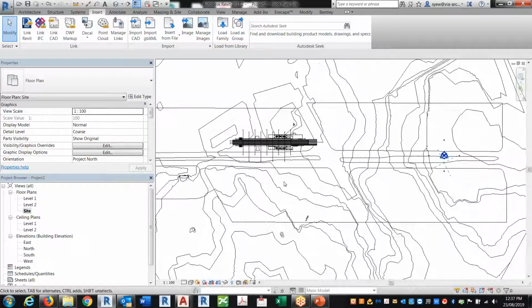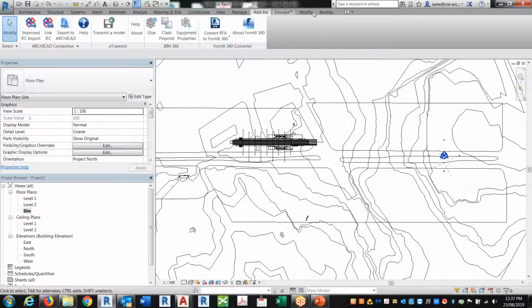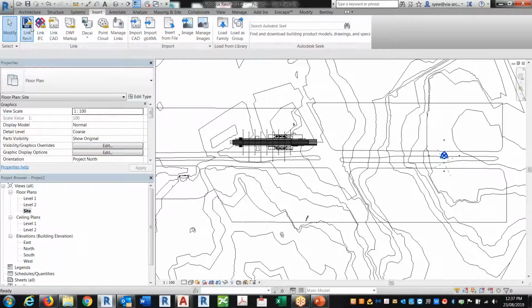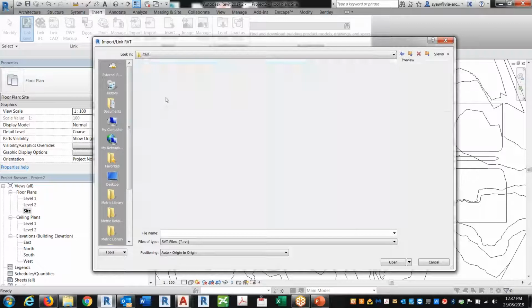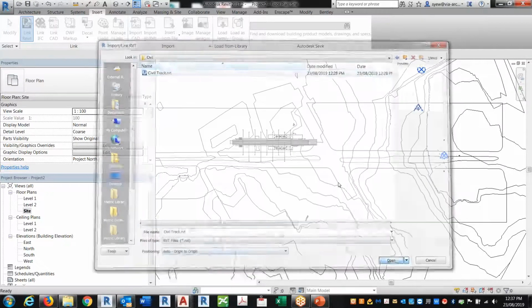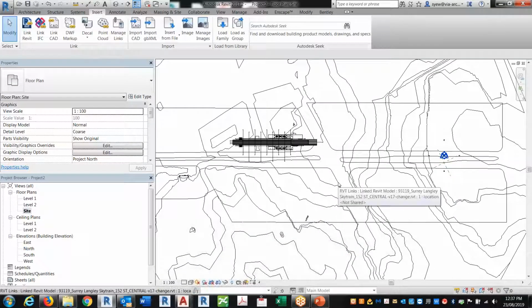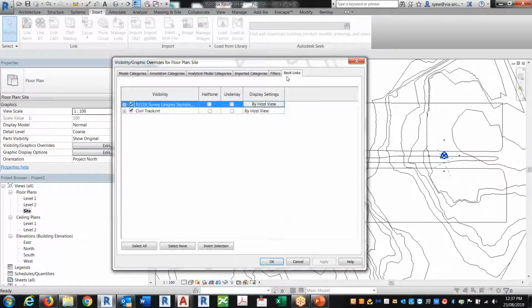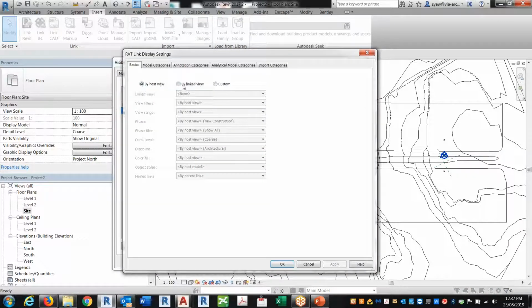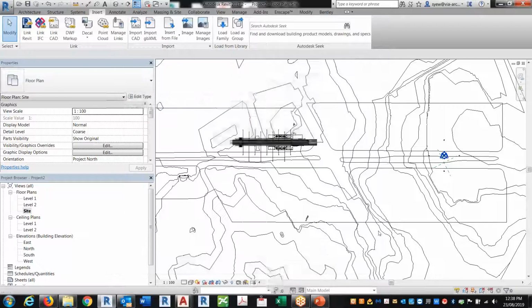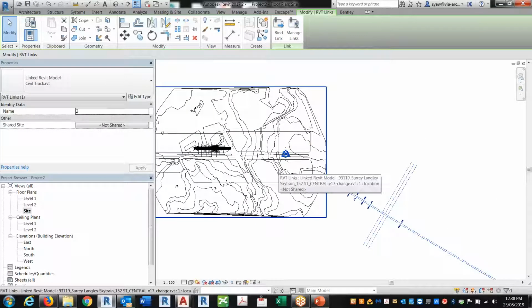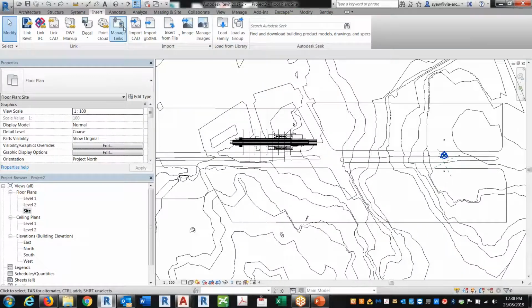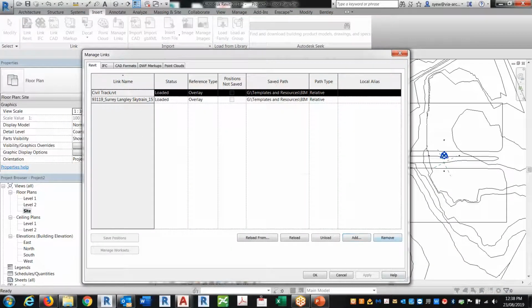Everything's fine. Now, if I acquire coordinates, like if I, let's say, link in that particular Revit file into this file, it would not work, right? So let's assume that here, if you go in and go origin to origin, it's not going to do anything. Okay, so if I go here, go to civil track, you notice that it's right there because it's origin to origin. I'm going to undo that. Let's see, get rid of that.